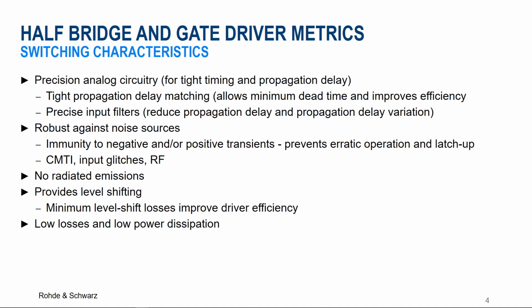Optimizing the system for performance and efficiency means getting the driver and timing as close to ideal as possible. Part of the challenge to these performance gains is increasing the switching frequency. However, higher frequency may result in higher switching losses, and system design is a bigger challenge. In addition to the challenge of tuning the system, higher frequency will also likely result in more ringing, noise, and radiated emissions. Timing mismatches should be well understood, not only for increasing system performance and reducing losses, but timing failures can also lead to unfavorable events such as shoot-through.